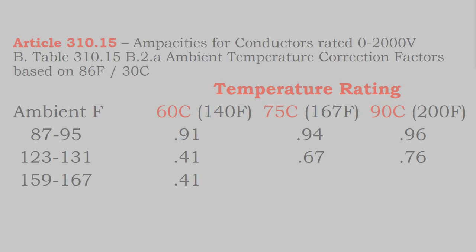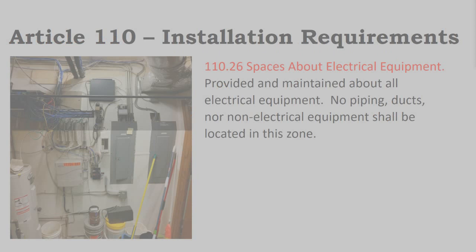And so in solar design, and when you're transmitting electricity from a generator to its point of use, you're balancing the environmental conditions, you're balancing derating the conductors, but then there's also efficiency, where often you're upsizing the cables anyway in order to make the system a bit more efficient. So we'll run through these calculations as we get into those sections a little bit later on in the program.